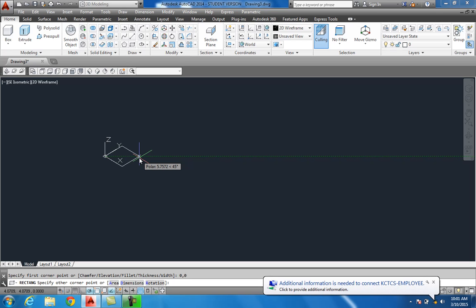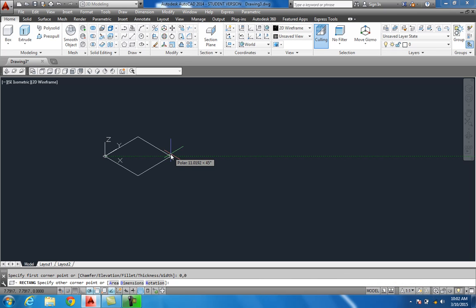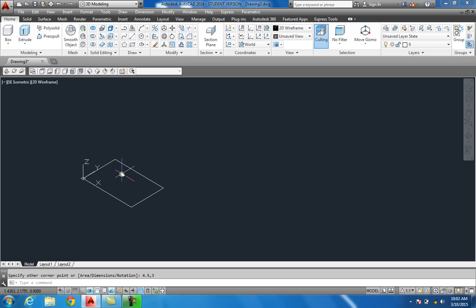In chapter 3, if you'll look in your book and find the Locator Design, it's a little isometric view of an object, and it's called the Locator Design, and you'll find it in your book in chapter 3. I want to draw this for you, and I'll show you how to get started. Now this thing is 4.5 by 3, so first thing I want to do is just type in your XY. Be 4.5 for X, and Y is 3. You see that?